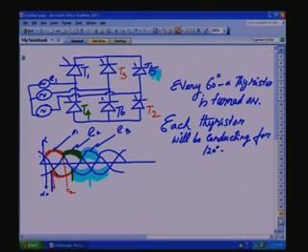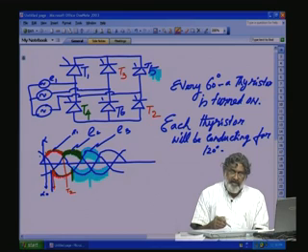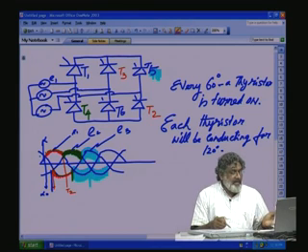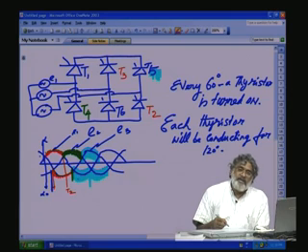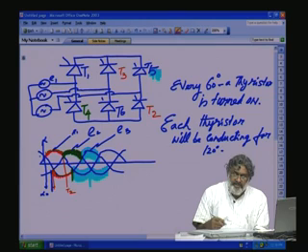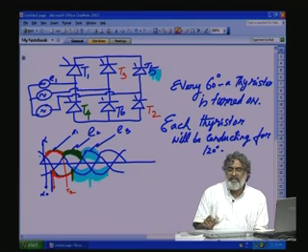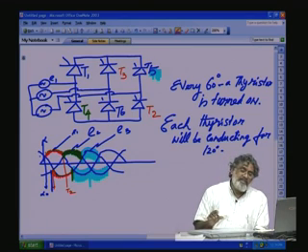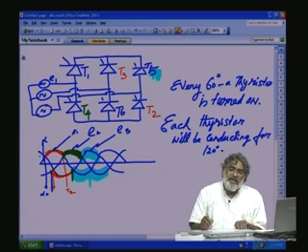Okay. So, individually we have written the ripple content for alpha is equal to 0 for the positive side and the negative side. So, what will be the net output ripple? The net output ripple will be the positive minus negative. If you see instantaneously, you will get the net output ripple, that you can do. The output ripple will have a 6 pulse content. In 360 degree, every 60 degree you are initiating, so it is like a 6 pulse waveform. The ripple frequency will be 6 times the fundamental.